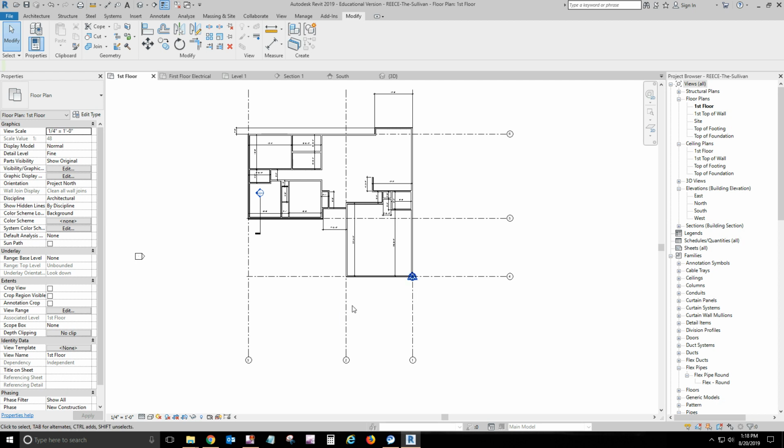Now then, these walls are 2x4 stud walls, half-inch sheathing, clapboard siding, that kind of stuff. So just like last semester, you want to copy a clapboard wall family into this project, and you can do it from going to your old project and opening it, select one of the walls, and then copy and paste into this project, or you can open a new project here by using the construction template, then draw a wall in the new construction project and copy and paste it into this one.